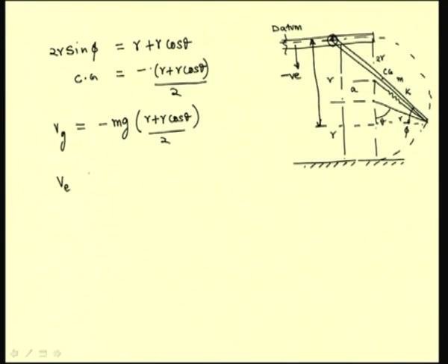Same way, let us write the potential energy associated with the spring. It is known that for the completely open position, that is when this door is in this position, the spring is in the unstretched position, that means the unstretched length is r minus a. So, for any given position we should find the stretch of the spring in order to compute the elastic potential energy associated with the stretch of the spring. So, for that we compute it as 2 times, because we have 2 such springs, 2 times half k, that stretch square, which is equal to 2 times half k.